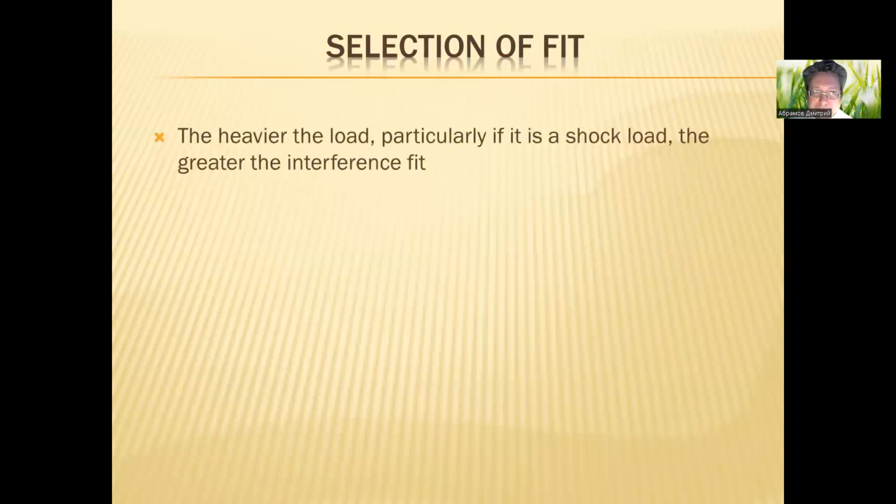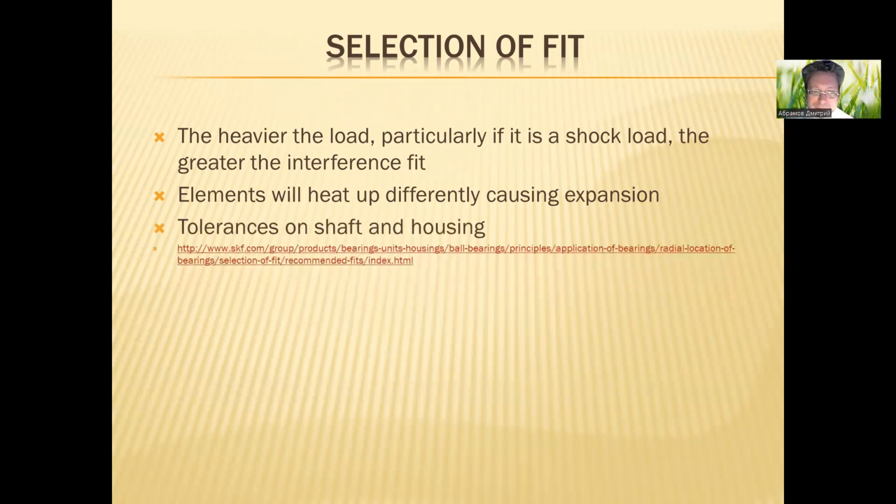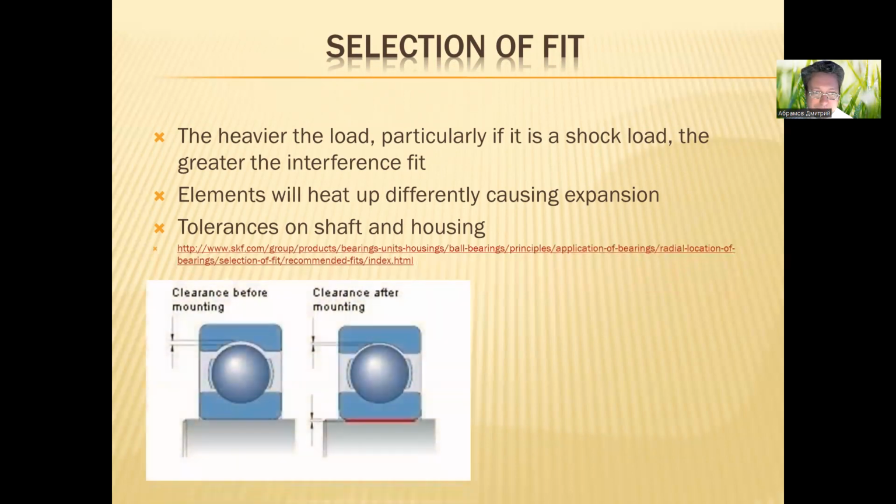Selection of fits. The heavier the load, particularly if it is a shock load, the greater the interference fit. Elements will heat up differently, causing expansions. Tolerances on shaft and housing. Clearance before mounting and clearance after mounting.